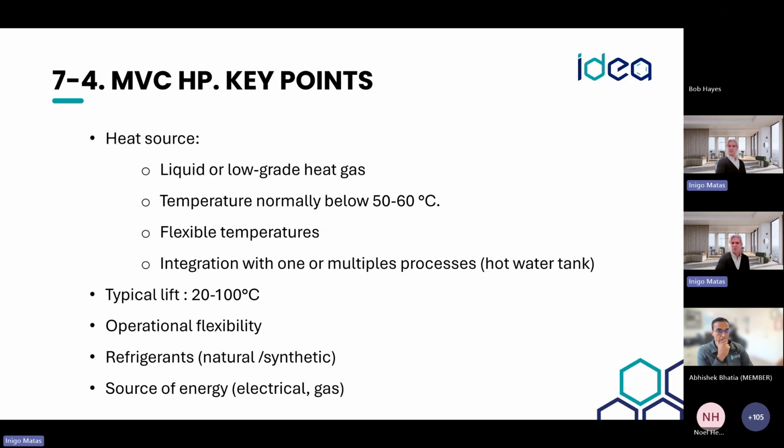We can have temperature lifts of 20 to 100 degrees, which are feasible depending on the compressor selection. It's good for allowing us to integrate multiple processes. If we have that hot water buffer, we can maybe have some recovery at lower temperature. We can also recover heat at higher temperature. So this gives a very good operational flexibility.